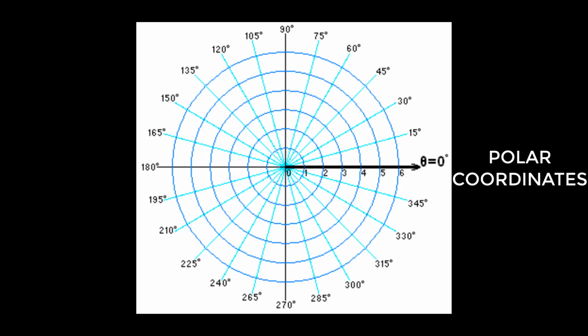Again, this is a type of relative point, so we are going to use the at symbol again when we talk about this. We are going to have to also explain to AutoCAD what we are trying to do. So in this particular case, we're going to use a different input method to tell AutoCAD that we are actually using a polar coordinate.